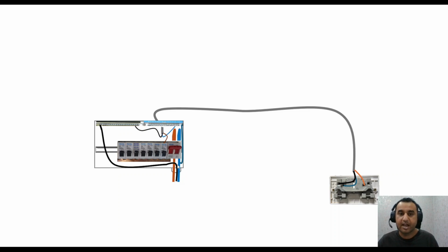As I said, this MCB is there to protect your appliances and this cable from getting overheated. Obviously, they should trigger. There's a misconception about MCBs. I've got 20 amp MCBs. If the load or overcurrent on this side is 20 amp or more, such as 22 or 23 amp, that doesn't mean this MCB is going to trip straight away. It could take time. It depends on how much current it's taking, and it varies from manufacturer to manufacturer as well.